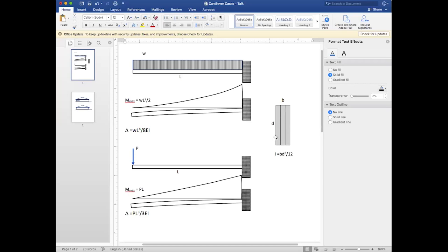But if you don't have a way of bracing it, in this case, they were glued and screwed together so that the cross section in one dimension was 1.5 times 3, 4.5 inches in width by 14 inches in depth. So that cross section doesn't require any additional cross bracing. It is stable enough that it will stay vertical the way that I've drawn it on the screen.